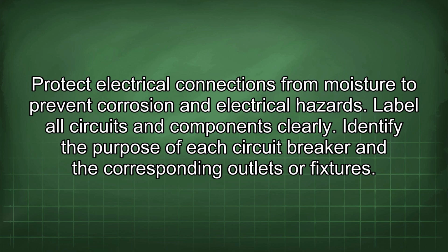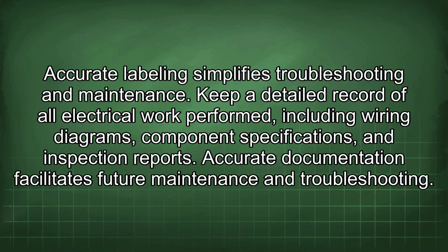Label all circuits and components clearly. Identify the purpose of each circuit breaker and the corresponding outlets or fixtures. Accurate labeling simplifies troubleshooting and maintenance.